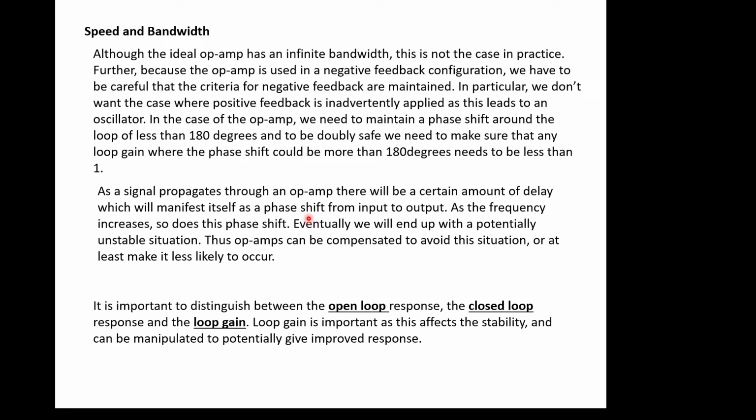It manifests itself as a phase shift in an AC system. As the frequency increases, the delay may stay the same, but the phase shift will increase because it will be a bigger fraction of a complete cycle. And eventually you could get to the point where you've got 180 degrees of phase shift at a certain frequency. And that's where the op amp has to roll its gain off, so that you don't get a gain of 1 or bigger than 1 in the feedback, because that leads to oscillation.